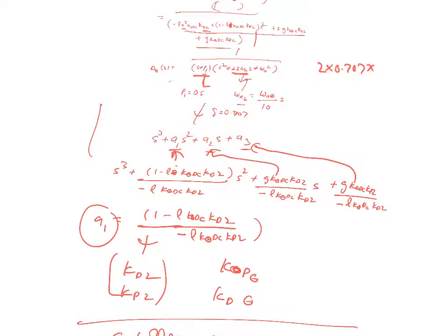And the idea is a big fixed wing UAV is flying with a rope or a cable attached to it with some kind of a drogue, right? The idea is, how should I move the UAV such that I get a desired trajectory for the drogue? So if I move the fixed wing UAV in a bigger circle, there might be a smaller circle here. If winds are there, then this will be tilted because of the drag. We have a paper for it, and this will be easy.